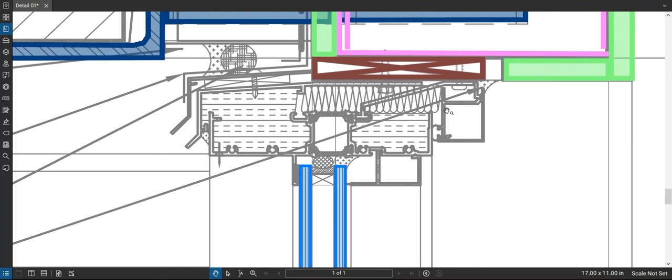So first of all, what is a window wall versus a curtain wall? A curtain wall is a glazing system that's hanging off the building, hanging off the structure. It doesn't have to be installed that way. But basically when you look at a glass office tower, it's going to probably be a curtain wall system where you have that look of pretty much full glass. It doesn't always have to be glass panels in there. There could be other panel type systems in there, aluminum or composite metal panels or what have you, instead of the glass. But generally speaking, it's this entire exterior wall system that's hanging outside the structure.